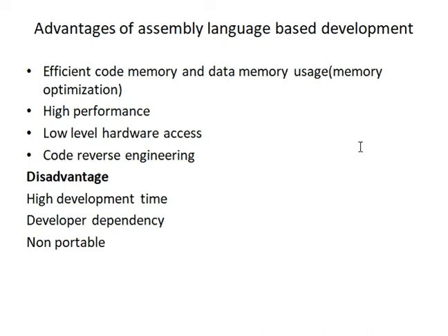But what happens when you compile using a cross compiler, when you convert a .c file into a machine file? Intermediately it gets converted to assembly code, and when you observe that assembly code, it would have 100 lines, just from the 4-line code you had, and many of the functions will be set to no operation. So this is not your optimized code.